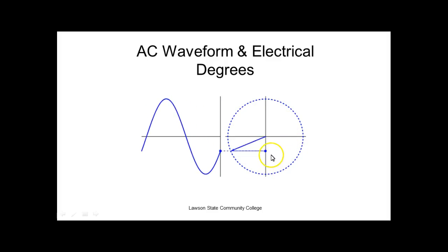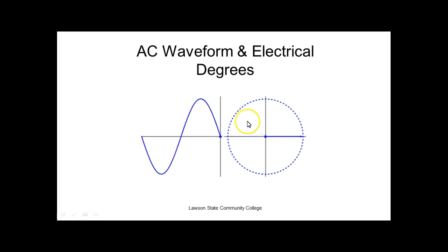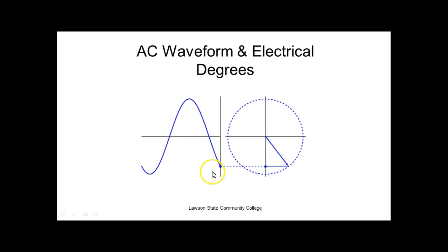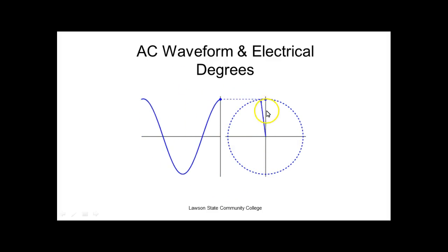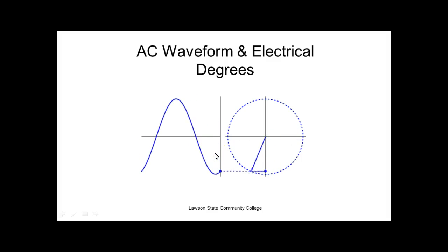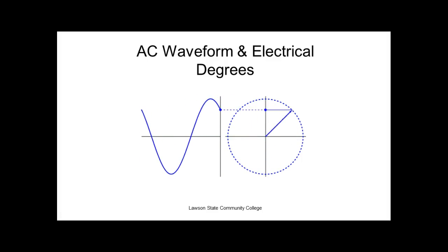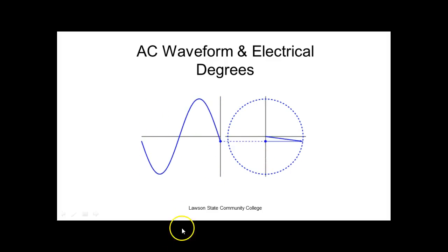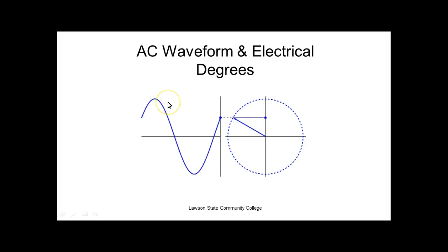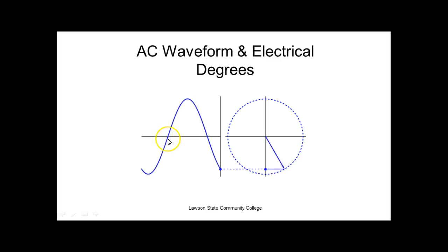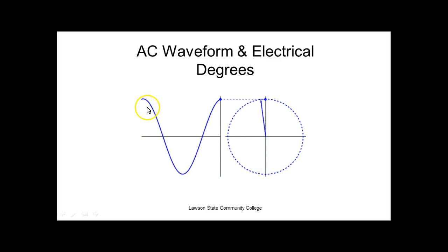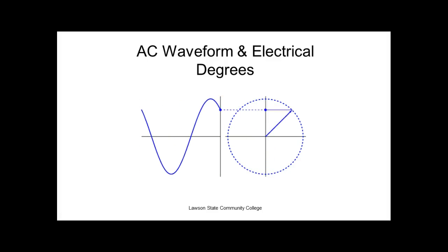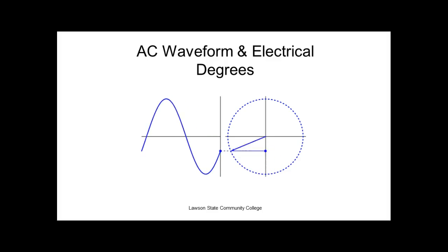So this is moving around in 360 degrees. And notice what we're doing is we're taking this point right here and we're transposing it over here. And what does it create? It creates this waveform called a sine wave. So it's not linear. Linear means it moves in straight lines. So my triangle wave would be linear AC, right? You understand that? It's not linear, which means the voltage at this point does not change at the same rate. So what happens is it starts off and as it moves on, the rate that it changes starts going down until it gets up to the very top, and then it doesn't change anymore until it starts dropping down on the other side.